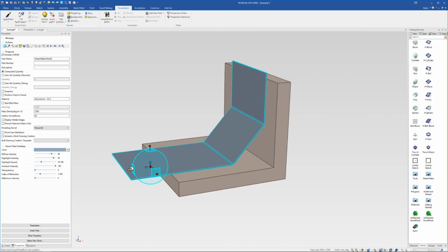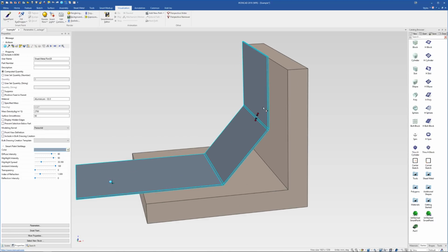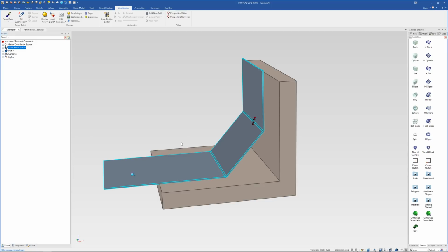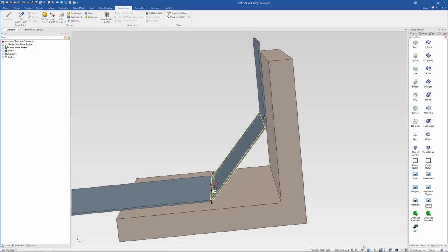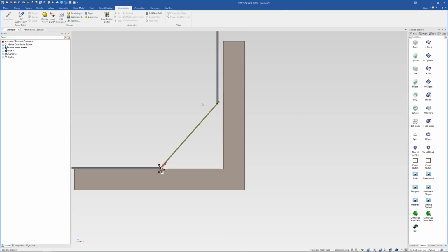So what you might sometimes find is that you've got this positioned into a position like this, where you want to actually size this sheet metal model. The left side can't move in your model that you're working on, and you want to size this so it hits that wall. And this side needs to stay the same size, but this is the only thing that can change. And so if you're just trying to get it there, like on the side like this, most of the time you can get it really close, but it's not exactly on there. I'll just turn off perspective so you can see what's going on.